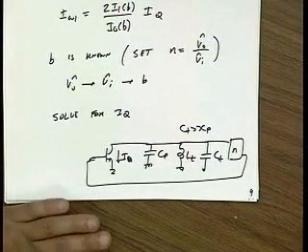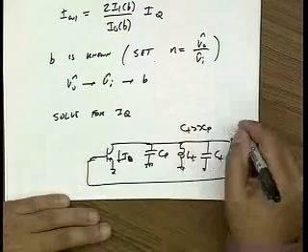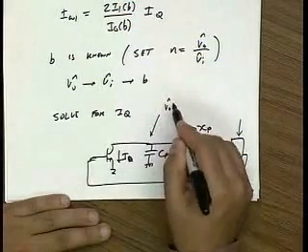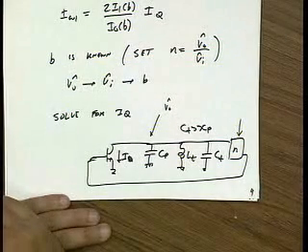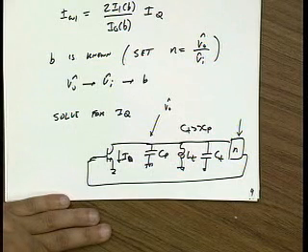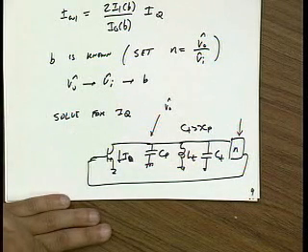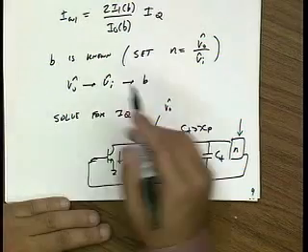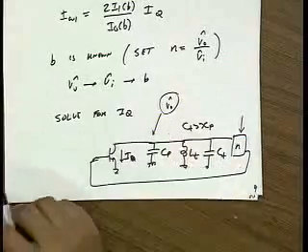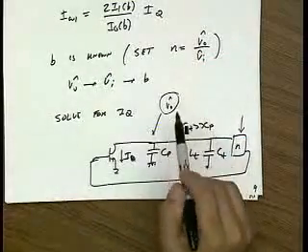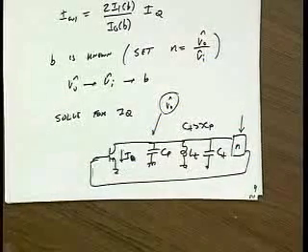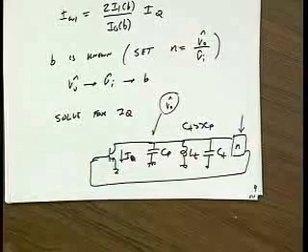Okay? And so you see there is some design freedom. We had the freedom to choose N. In some ways we also had the freedom to choose VO. In some situations we don't. We need full rail-to-rail or close to it to get the best performance. But for now, let's just focus on the free parameters. Because there are so many design variables, we outlined a procedure: if you fix VO and N, then everything is known. You can basically find all the components.